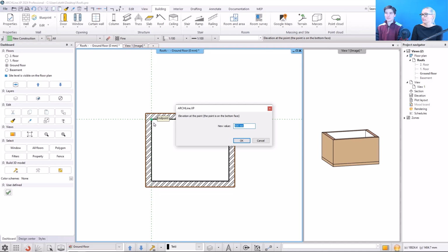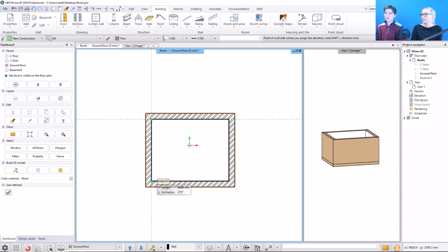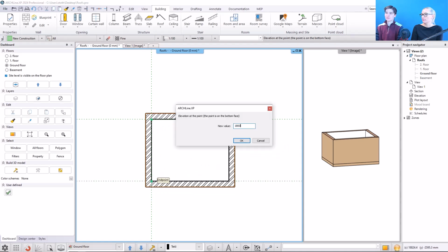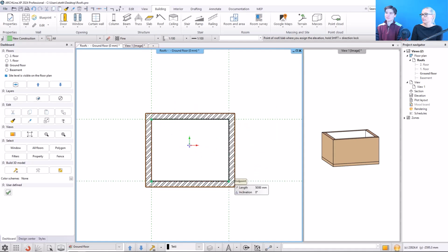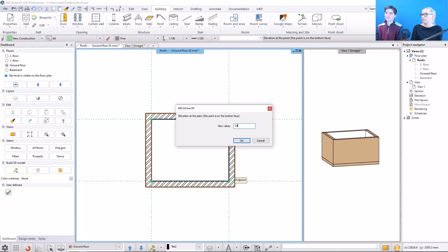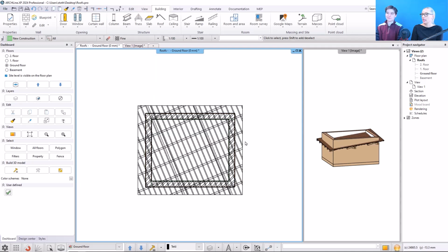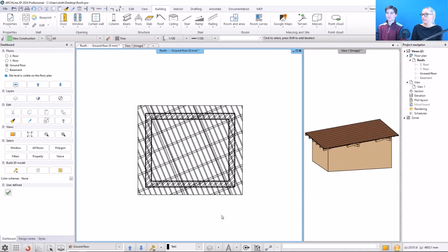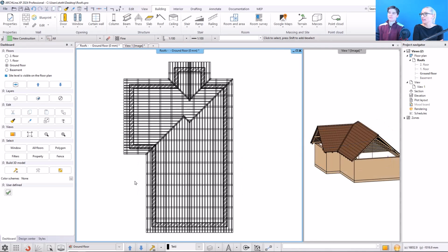Yes, let's do that. I will define the roof height on the inner side of the walls. I will enter 3 different values. And it's done. The building needs a little more adjustment to properly cut the walls. I will rebuild the 3D model and the program will automatically cut the walls. That looks much better. Let's look at the modification where we customize the framing.